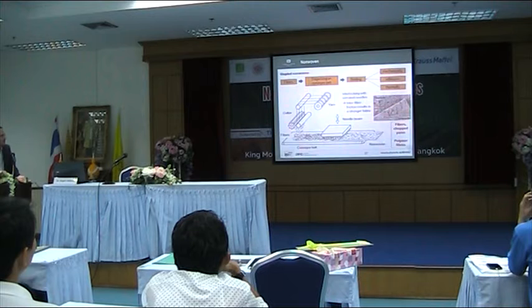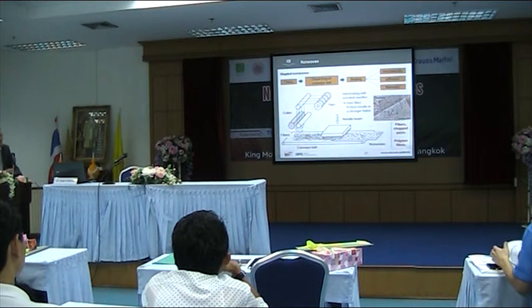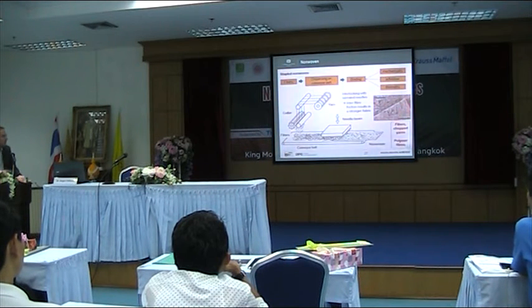So you can use these classical processes also for natural fibers and for fiber reinforcement, but the problem is in the small process parameters and small things. We have to look at the geometry of the feeding system, of the needle system, and so on to get these prepregs. This is much inside knowledge of the textile producers and producers of textile machines for technical reinforcement.